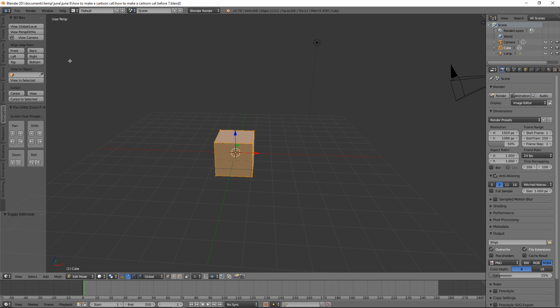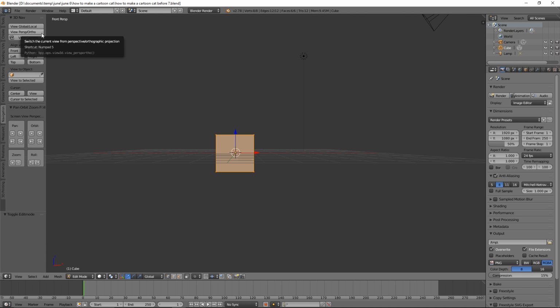What we're going to do now is click here to go to front view. We're then going to click here to go to what's called orthographic mode. Right here you can see we're in front perspective mode. Perspective mode is kind of like a 3D view mode where you can see more of your object and how it looks, like it's in 3D. We want to actually make our object look like it's in 2D for what we're about to do. So to do that, see where this says view perspective / ortho. We'll click here and now you can see this says front ortho, which stands for orthographic, which basically means kind of like a 2D blueprint like view, which tends to be easy for doing certain things that you do while modeling, like what we're about to do here.